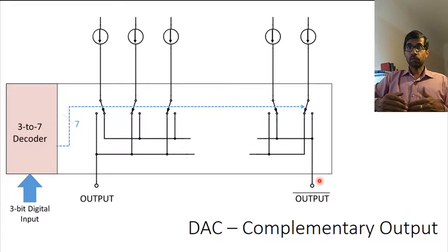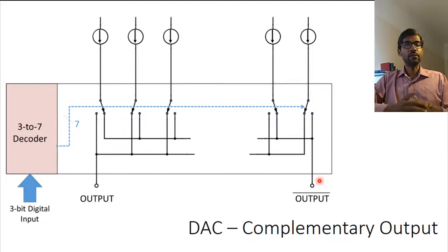And that's why, when you actually look at DACs, you would see that many DACs have complementary outputs, output and output bar, especially DACs which have current outputs.